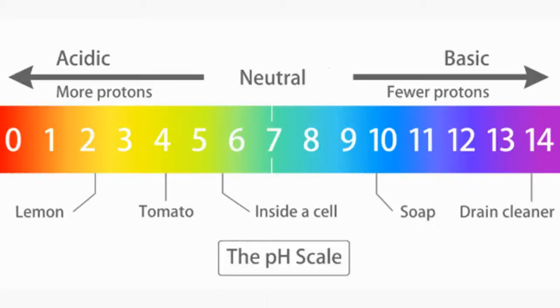There are 2 types of chemicals: acids, which have a pH lower than 7, and bases, which have a pH higher than 7. Bases tend to be good at removing biofilm, and acidic chemicals tend to be good at removing mineral buildup. Acids and bases should not be stored together and should not be mixed together. You should not use any chemical you are not trained to use.